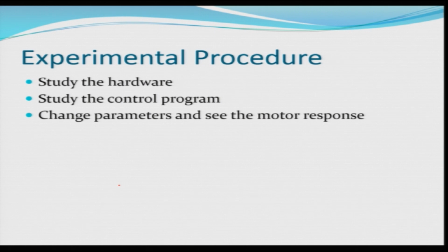So, this is one step higher control compared to the manual control, wherein we will have the facility of changing the delay, changing the speed, changing the direction, or changing the number of steps that the motor can move, or we can move the motor in a number of rotations also. Similarly, there can be a closed loop control wherein we can have some I/O depending on the sensors or any other signal, so that the motor can be controlled.